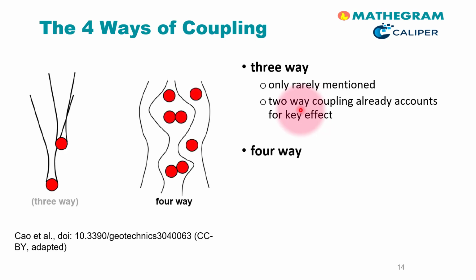The ultimate coupling approach is four-way coupling, which is realized by all available CFD-DEM models and is illustrated in the right panel. This way of coupling gives us full freedom of the application of a CFD-DEM model, meaning that it is also useful in high mass loading and high particle volume fraction applications.